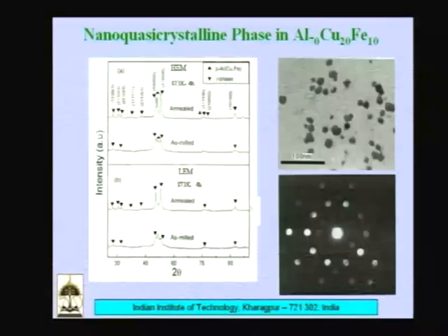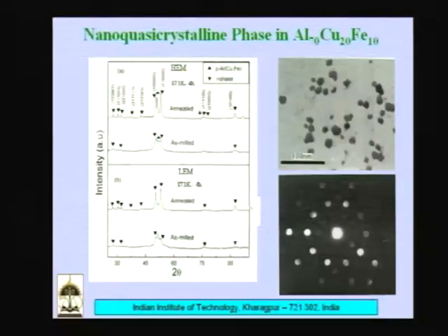Okay? So, you can see this case where you can have nanoparticles of a quasicrystalline case. As I told you last class, the diffraction obtained from a quasicrystal is entirely different from that of a crystal. Why? Because you have a special rotational symmetry in a quasicrystal, that is a 5-fold symmetry, and you can see here that if you look at the transmitted spot and count the total number of diffracted spots around that, you see 10 diffracted spots, which is what we call the 10-fold symmetry, and that is the classic example of a quasicrystal.